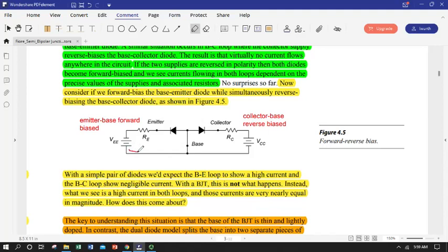So now we have positive current trying to flow into the P material and out the N, and of course that's going to mean this is in forward bias, so check mark, current could flow, and nope, not so much there. This one's in reverse bias. So we forward biased our base emitter loop and reverse biased our collector base loop.